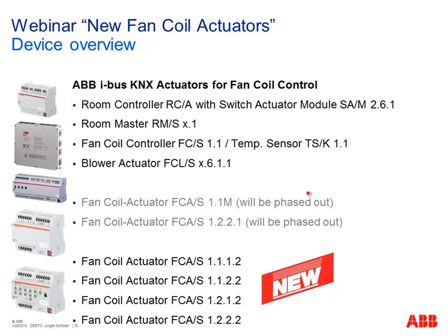Before we come to the new device, just an overview of the existing fan coil actuators we already have. These are the first four here. Our room controller, this box here, is available with fan coil control. The room master, typically for hotels. Then we have our earliest version of fan coil. It's not only an actuator but also a controller. Means you can connect only a temperature sensor here, and you have complete temperature control available. It's been in our range from the beginning, but not so often used anymore.